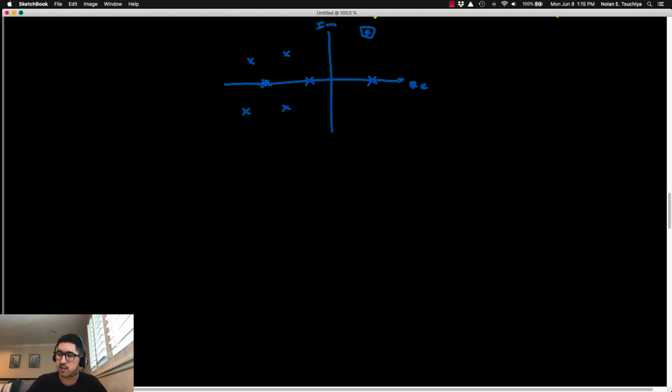One way to look at that is that the components of the response are directly related to the pole location. So for example, if we go back to this example here, what I see is a fourth order transfer function, right? There's four poles, so you're going to have an s to the fourth in the denominator. But what I see is one pair of complex poles, one real pole that's stable, and one real pole that's unstable. So for whatever transfer function this is, if you were to take the inverse Laplace of it, which again is equivalent to the impulse response, you would find that you get three components to the response.